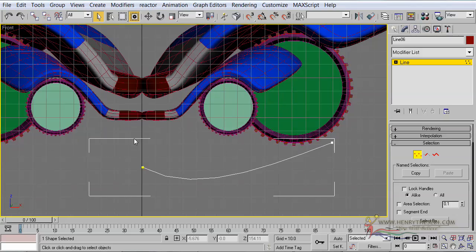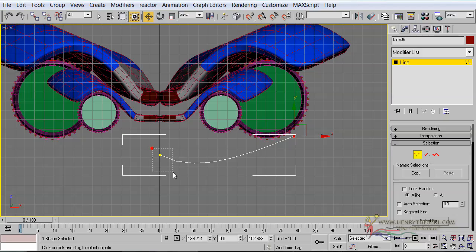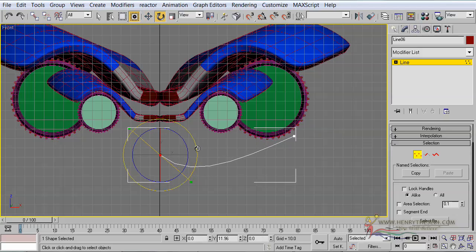Now what is the most important thing here is that the space in here will determine just how big a weapon this robot of ours can carry. But before that, let's just make sure that this side here will be closed off, and also select this section here. We just want to create a bigger gap or a bigger curve there, as you can see. Then select the moving tool, and we want to position it at 0 units on the x-axis, so that of course it's sitting perfectly in the middle.